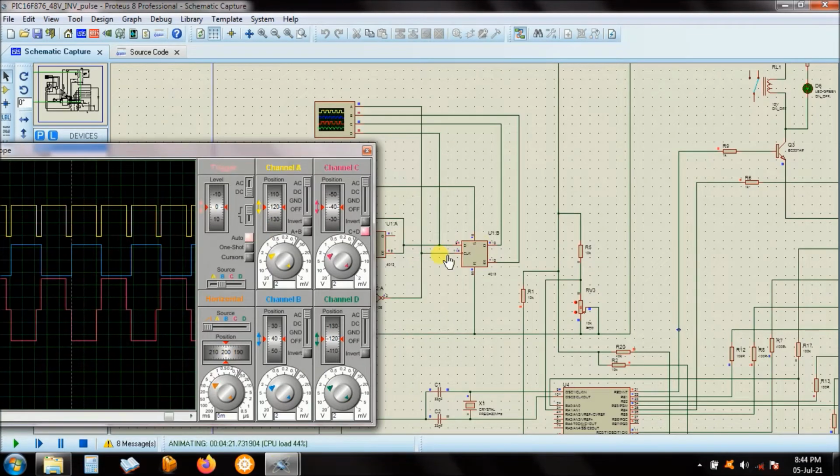You should actually be careful when you connect the outputs of these ones to the MOSFETs, because there's a point where you have the signal very much small, maybe to a point where it is actually zero, no output at all, because the MOSFETs are not even driven at all. Let me just stop and show you what I mean.